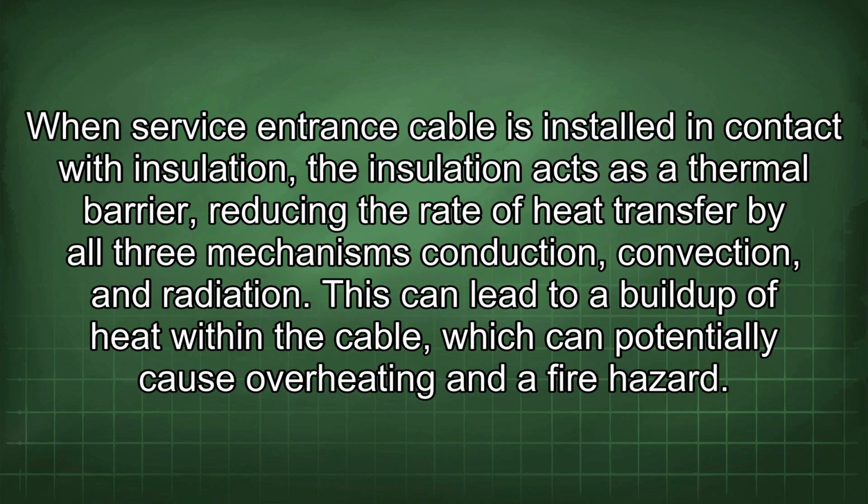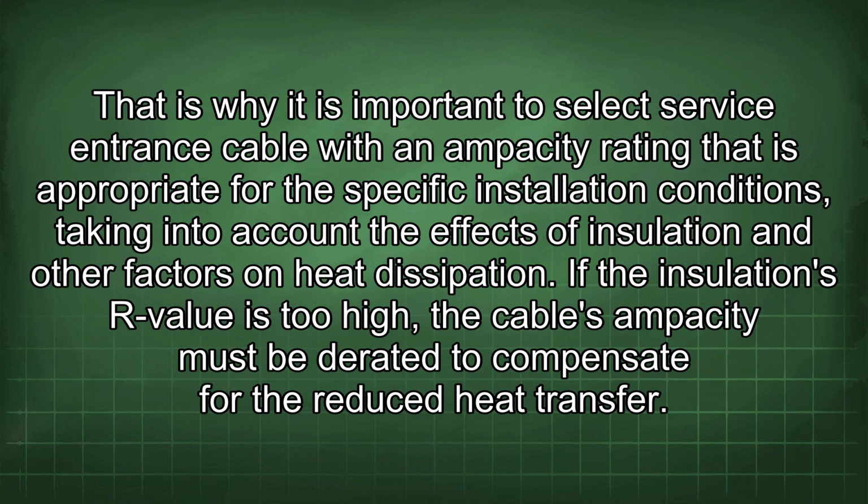When service entrance cable is installed in contact with insulation, the insulation acts as a thermal barrier, reducing the rate of heat transfer by all three mechanisms: conduction, convection, and radiation. This can lead to a buildup of heat within the cable, which can potentially cause overheating and a fire hazard. That is why it is important to select service entrance cable with an ampacity rating that is appropriate for the specific installation conditions, taking into account the effects of insulation and other factors on heat dissipation.